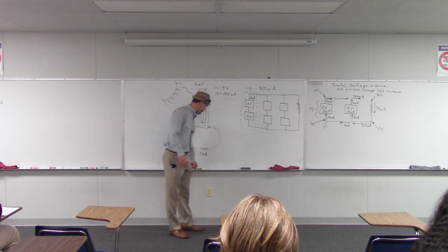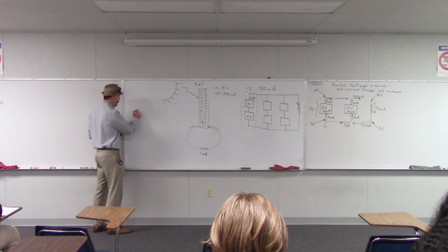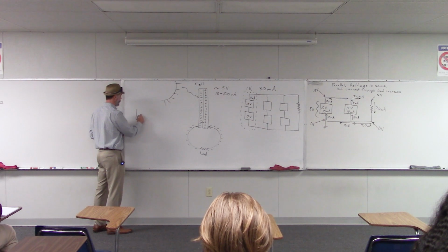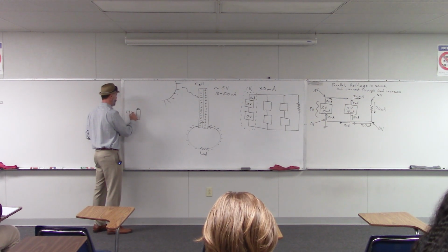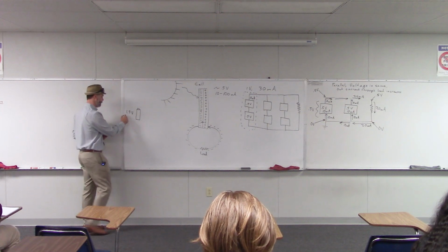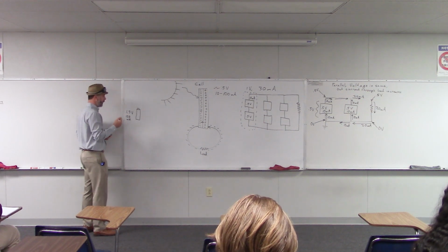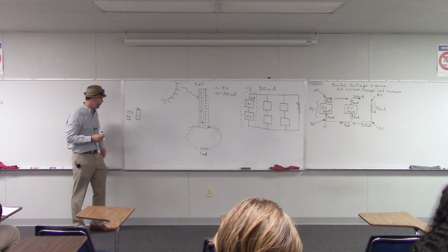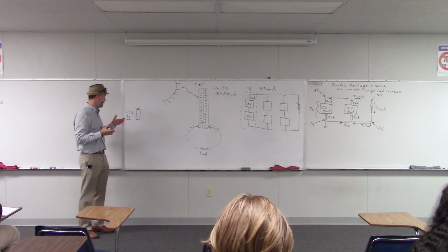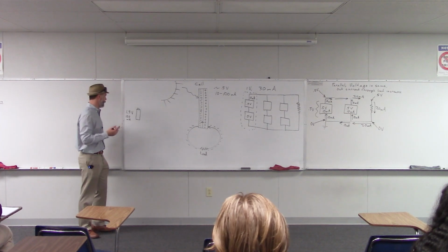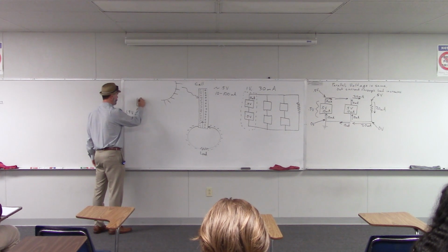So, for instance, one AA battery has about 1.5 volts and maybe 100 milliamps that it can provide. So if your toy, your little remote control car, needs 6 volts, then you could put 4 of these batteries together in series.